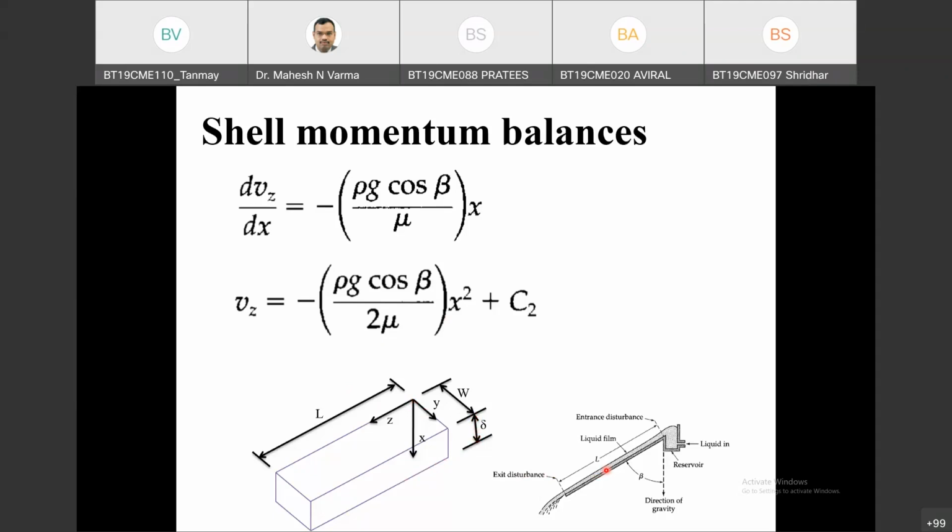At this surface, here I will have liquid solid interface. And at liquid solid interface, according to no slip boundary condition, the velocity of the liquid will be equal to velocity of solid, and solid is at steady condition. So this plate is not moving, plate is steady. So certainly the first layer of the fluid here will be having a velocity 0. That boundary condition I can put.